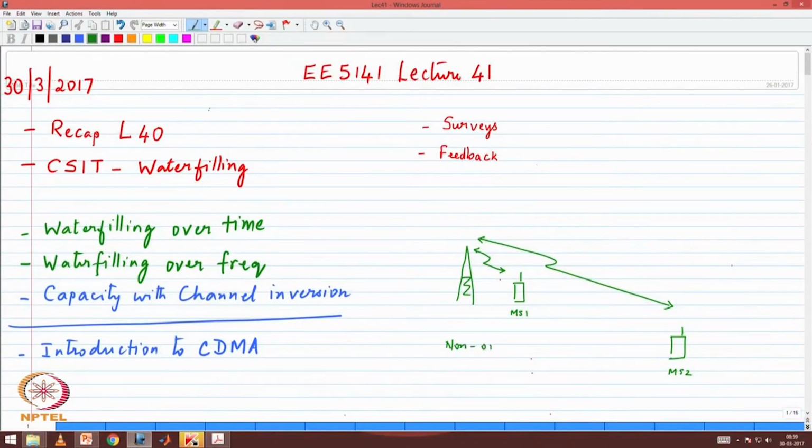However, if there is a scenario of non-orthogonality, that loss of orthogonality, one such scenario that can happen is, let us say they were on adjacent channels. So at the base station, mobile station 1 is like this, the second signal is much weaker. So when I try to filter out mobile station 2, I will get a significant portion of mobile station number 1. So this is the filter that is applied, and you can see a significant portion of green is leaking in, and therefore will cause me disturbance.